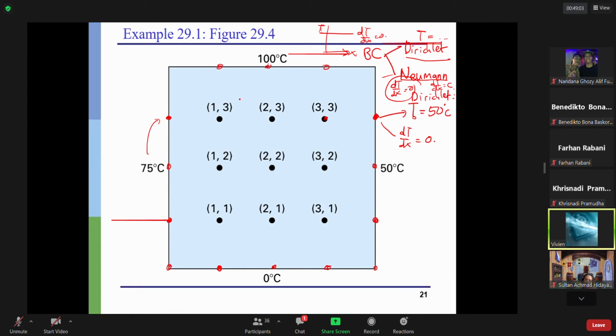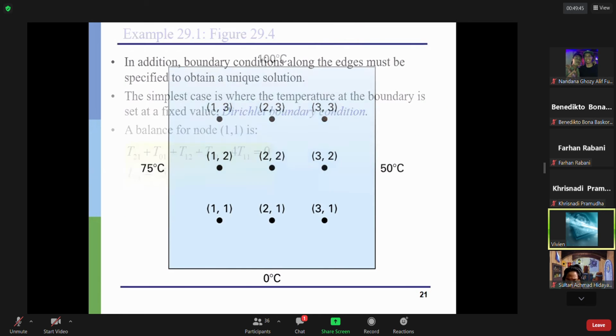So if we apply the Neumann boundary condition, how can we calculate the temperature? It means that we don't know the temperature yet, so this should be calculated as well. The information that we have at the boundary is the gradient. We also need to find the temperature, because it is unknown. It can be obtained by calculating from the domain inside. When we have the temperature inside, we can calculate the temperature at the boundary. So in general, we have 2 types of boundary condition.